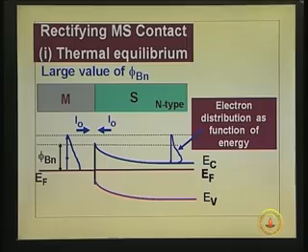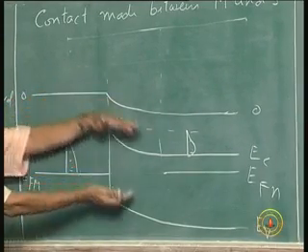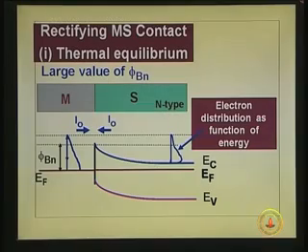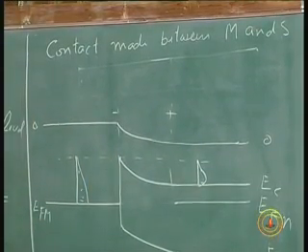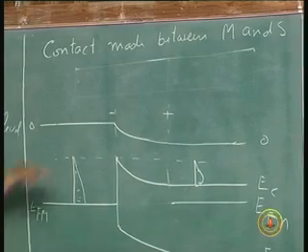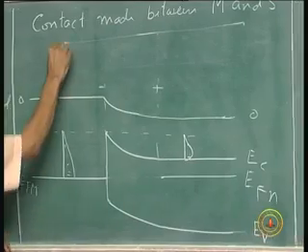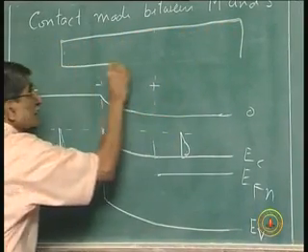Okay. Now, the main point that I wanted to point out was this: I have not shifted anything here, I have shifted the whole thing down with the variation there. Okay. Now, let us go to the case where you forward bias it, reverse bias it. Now, notice also this potential is like this, plus minus. Now, when I apply a reverse bias to this junction, I think I could have retained the diagram, sorry. So, let me redraw that here, keep it.